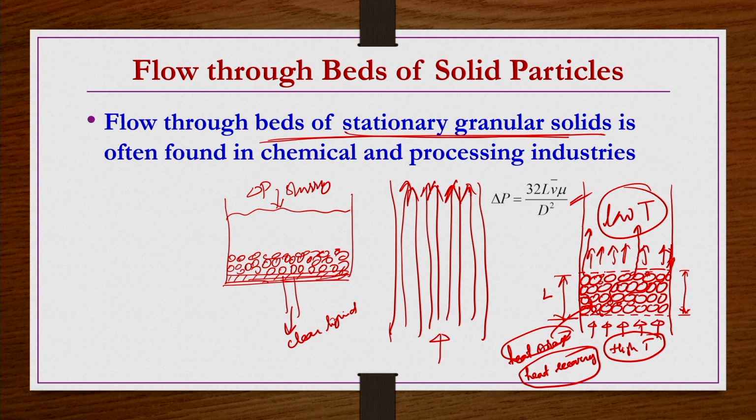Here, the particles present in the suspension are going to offer some resistance once they settle on the filter medium. So, this can also be taken as an example where flow through a packed bed is taking place. Initially only the filter medium is providing the resistance to the flow, allowing only the fluid to pass through and retaining the particles, so that the separation takes place. But gradually, as the process progresses, these particles settle on the surface of the filter medium, and they additionally add resistance to the flow for the later incoming slurry.